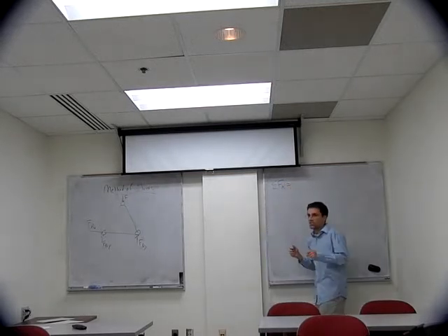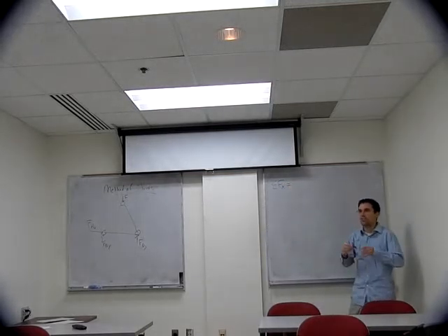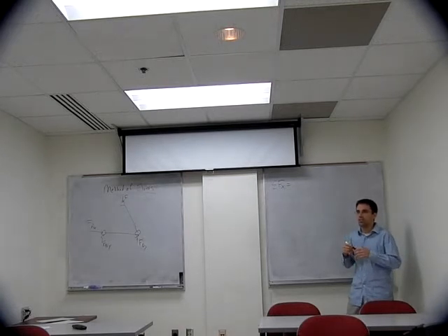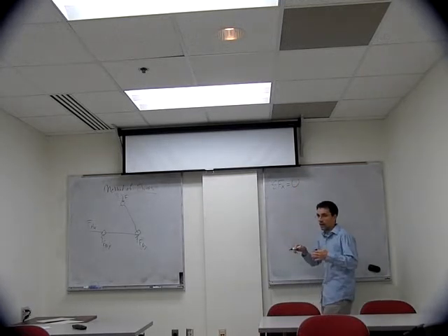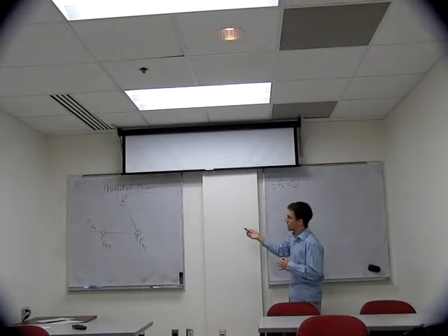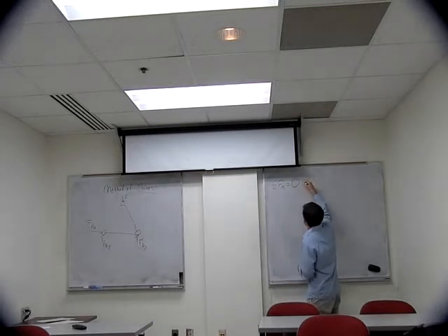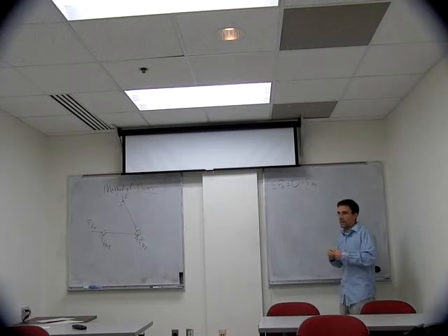And since this is a static system that's in equilibrium, we know that the summation of all these forces has to be equal to 0. This is the definition that we can rely on. And we see here that there's actually only one force in the x direction. So FAX is going to be equal to 0.